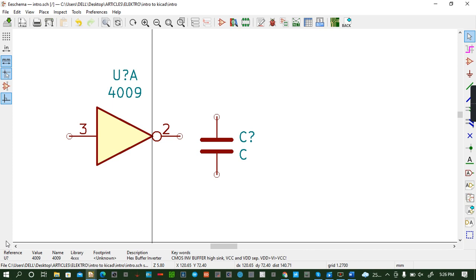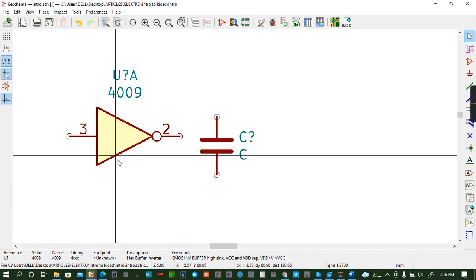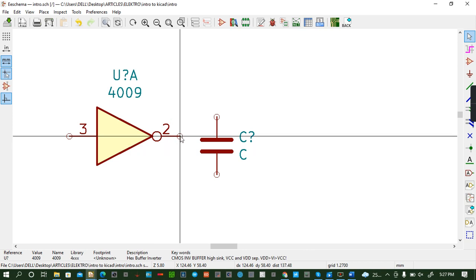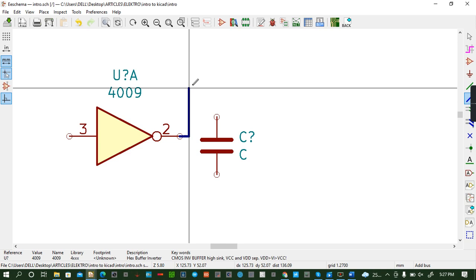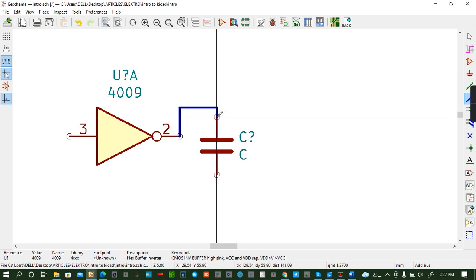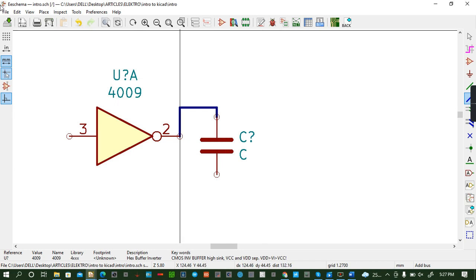And then A is for adding component. I had introduced it. If you hit A, you will be adding components. And then if you hit B, you will be beginning bus. You know how to begin bus, it begins to connect. So for example, I have it there, and then I hit B. You can see now we are moving the bus like that, like that. It has connected.